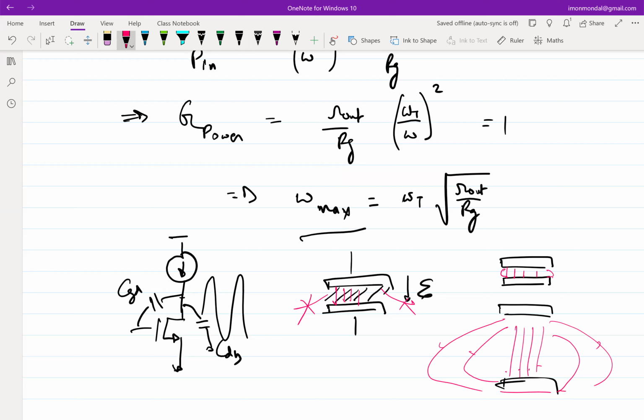So which essentially means that your capacitance models are more accurate here and less accurate here, because you have fields bulging out, maybe going somewhere else also. And after some time, it is not even going to behave like you double the area and the capacitance need not necessarily double, because your fields are going away.